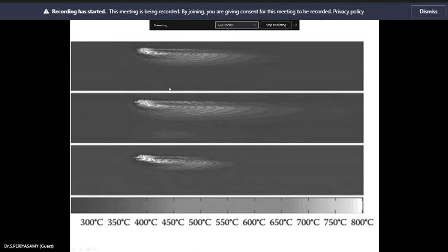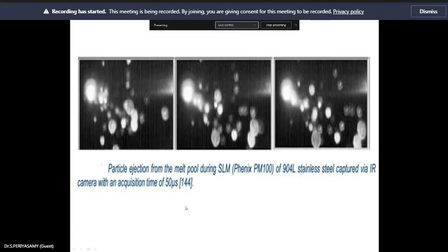Then the electron beam melting: the process parameters may have a significant effect on the part quality, indicated in the variations. The melt pool, that is the previous one, the scan, the beam current and the scan speed affect the EBM build, such as porosity, which may be related to the microstructure or a property variation in the final product. Even delamination is also possible.